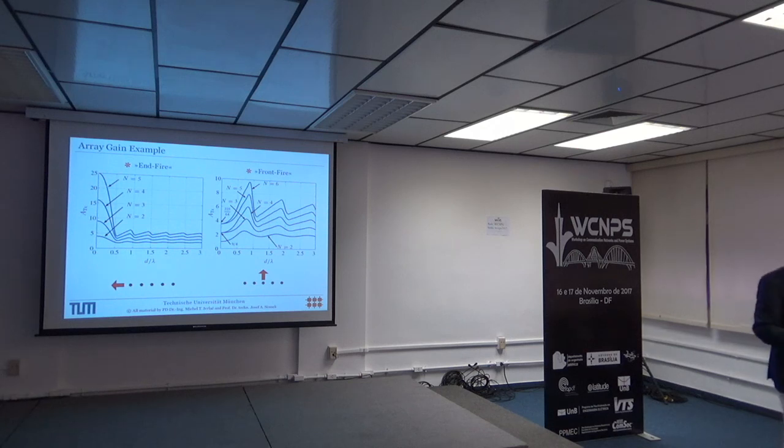That end fire is better, you should have known. Think about in the past when we had still standard terrestrial TV reception with these Yagi-Uda antennas, which are multi-element antennas, and they always were in end fire direction, pointing to the transmitter, and never in front fire.